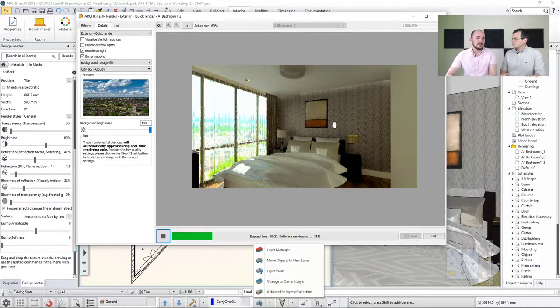And the reason why it's important is, imagine the building where we are now. We are in a larger office building, in one office, in one room of that office. Now this office has several rooms, so if I filtered my model before rendering this room to only these light sources, these lamps, these objects, I can simply shorten the rendering time, because the software wouldn't have to calculate all the rest of the rooms. It just works with this part of the room.